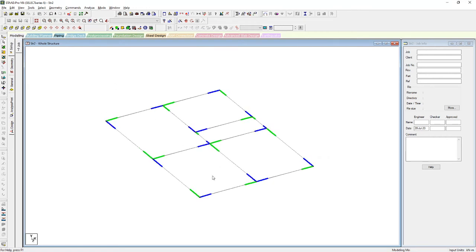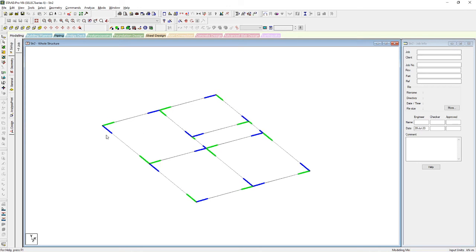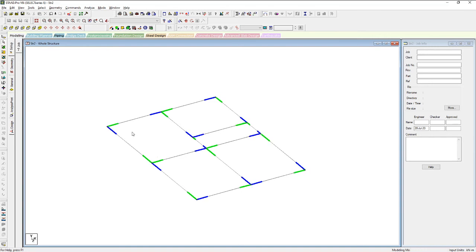So how do you determine if you modeled your plan correctly? You need to determine if all your beams start from your 0, which is shown if it starts with green and ends with blue, that's correct. It shows here that these along Z beams start with blue. So you need to redefine all members that start with blue. So simply select these members.